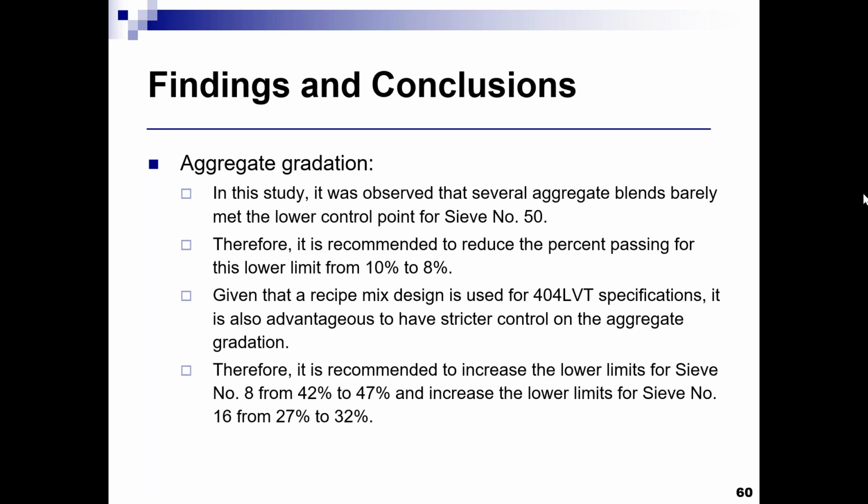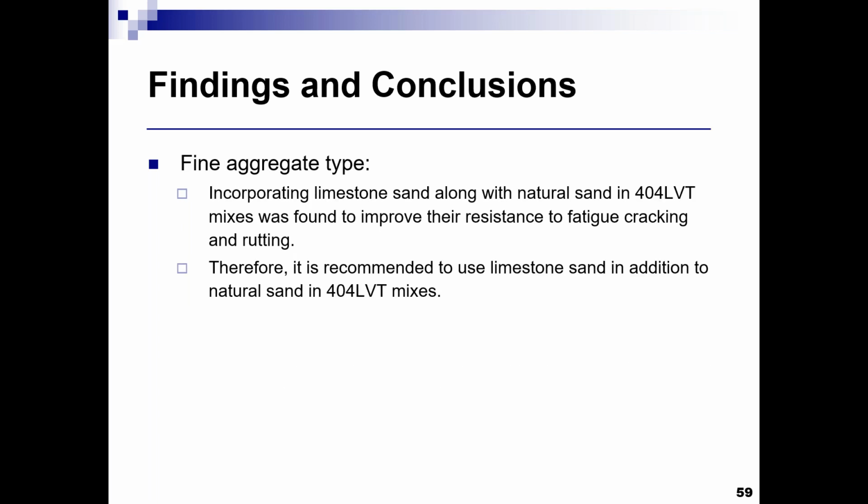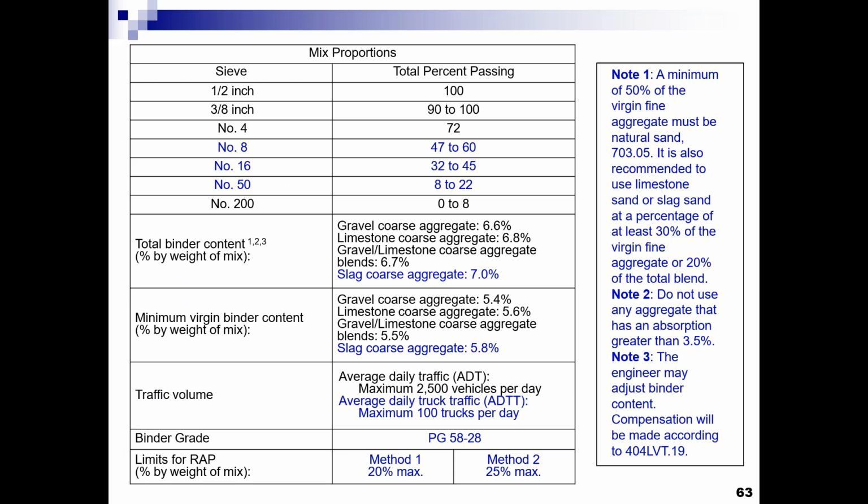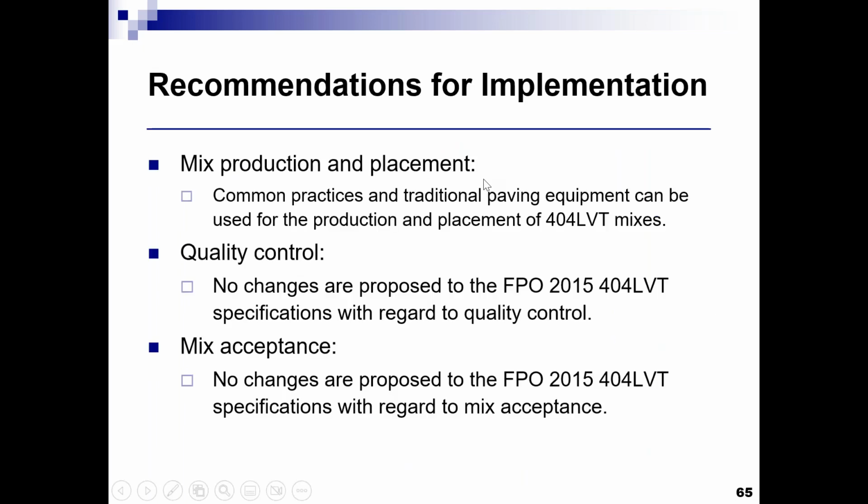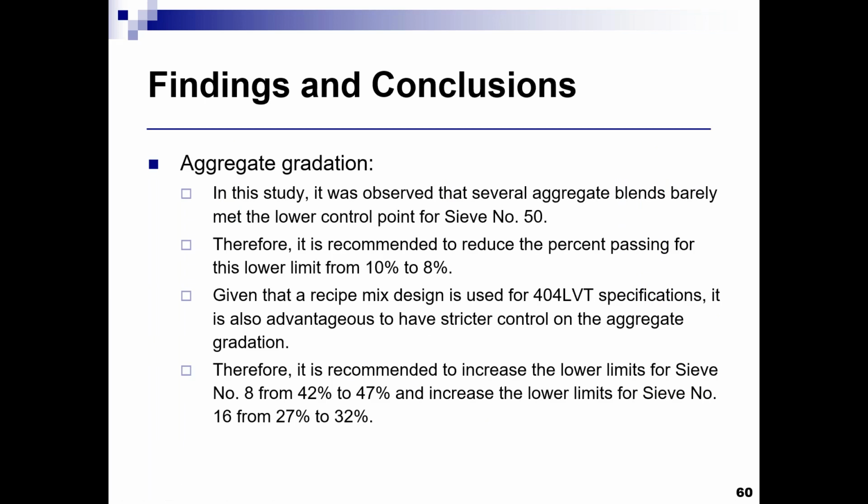Same question, increasing number 8 and number 16 by 5%. So these ones are, again, same answer. As long as you can get to meet these gradations with the available aggregates, you're okay with modifying the gradation limits as long as the mix performs basically well in the lab.